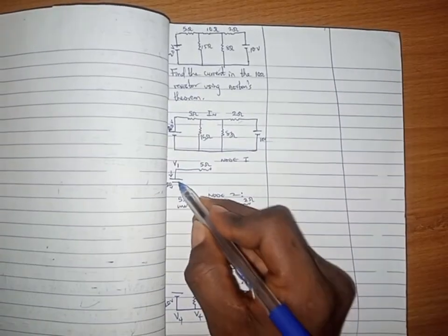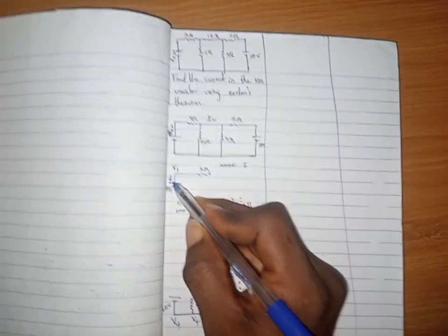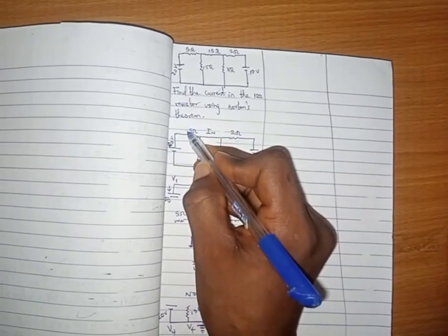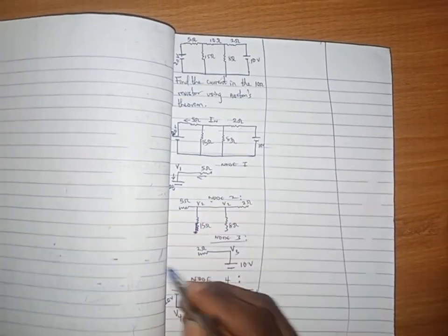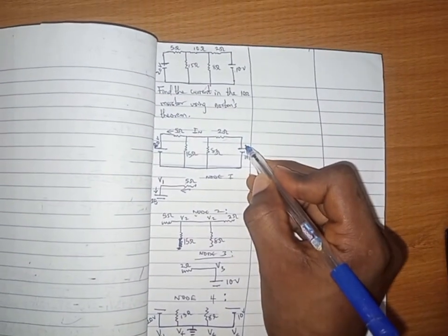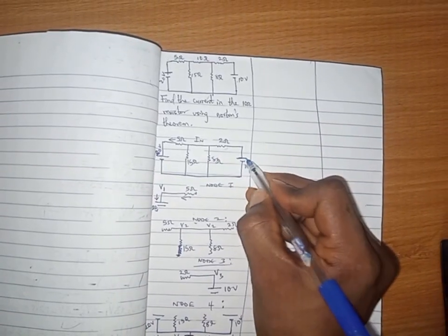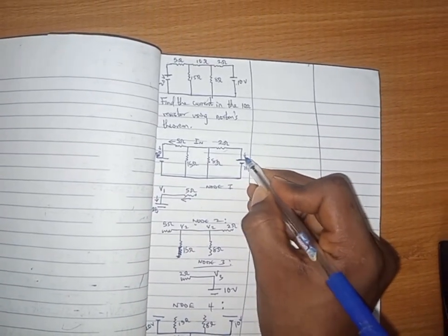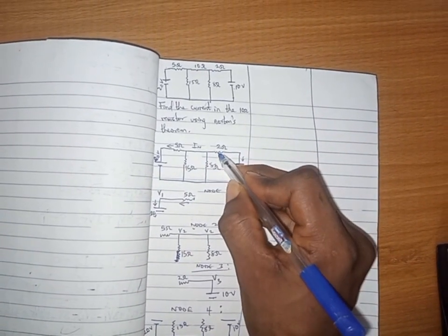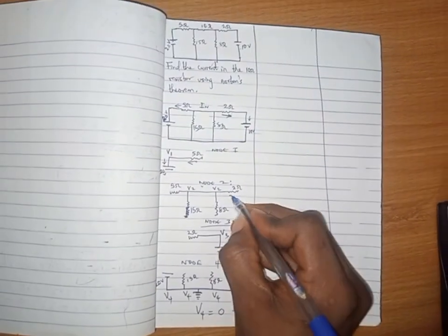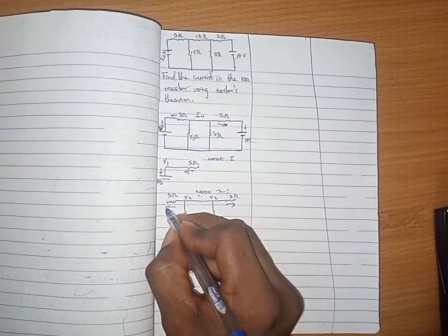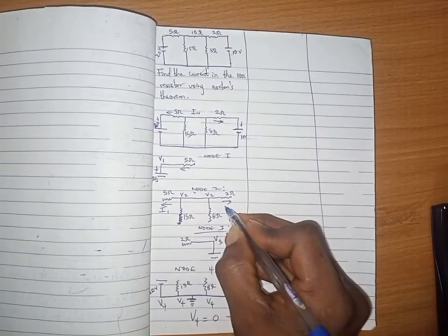Since that is the case, if this is entering, which current is this that is flowing? Is this the 5 ohm, which is here? So it's moving from here, which means the direction of this current is this way. Now, this is the positive side of this battery and this is negative. Current enters here. Which current is this entry? It is the current traveling through this 5 ohm resistor, which means it's going this way. So let's call this I1.